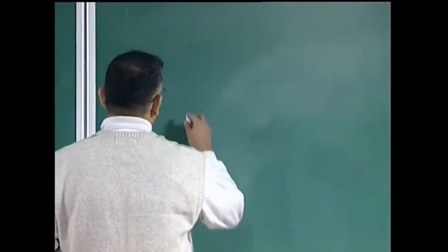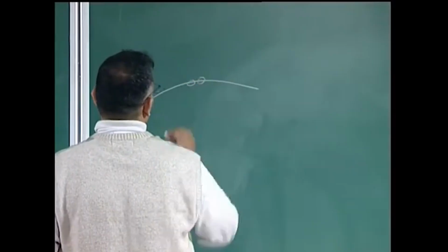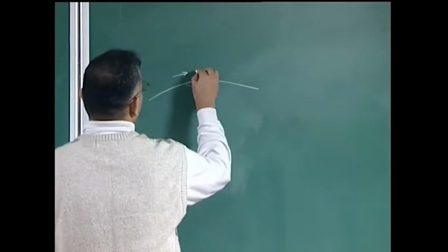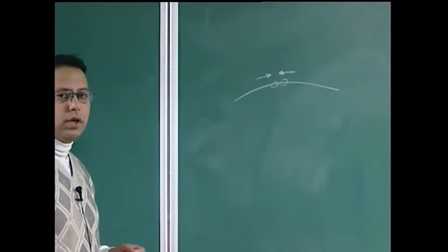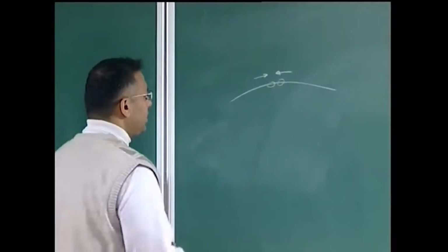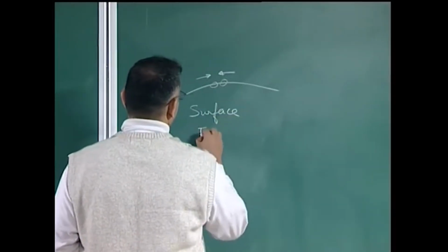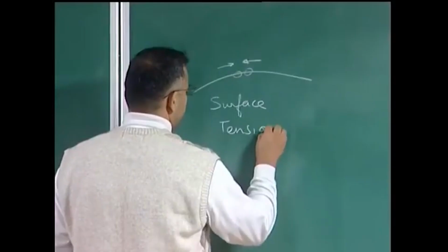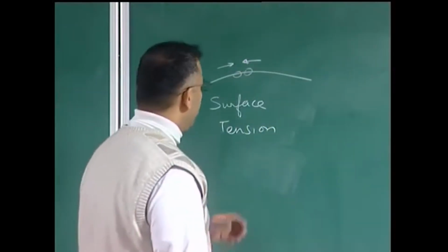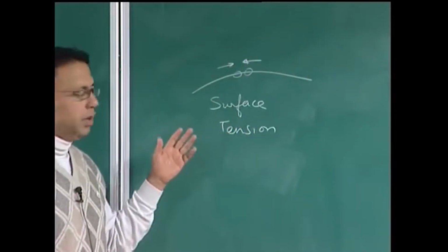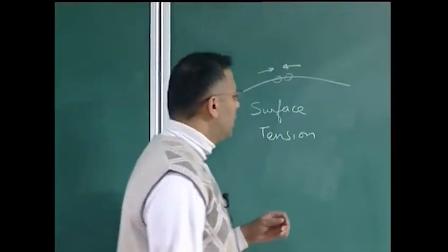Suppose I have a metallic surface in which there are atoms, and the surface itself wants to contract to reduce the surface energy, because the atoms sitting on the surface have a higher energy, and this is the origin of the surface tension. And this surface tension effect can lead to a lattice parameter contraction. But now, we know in nanoparticles the overall surface area, or the surface to volume ratio, is very large.